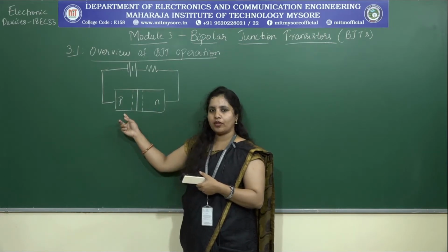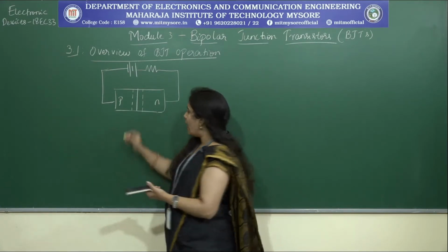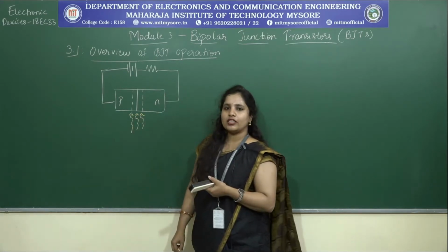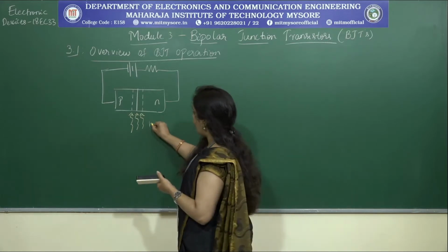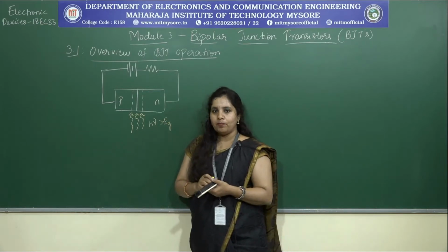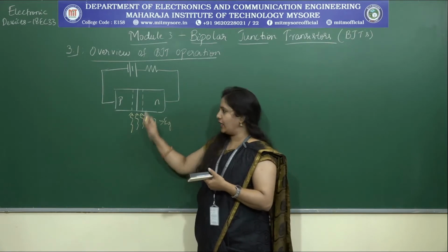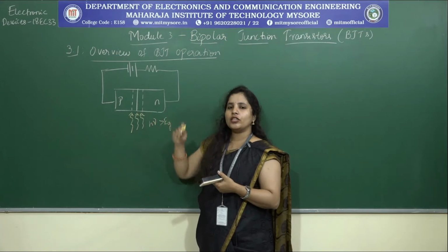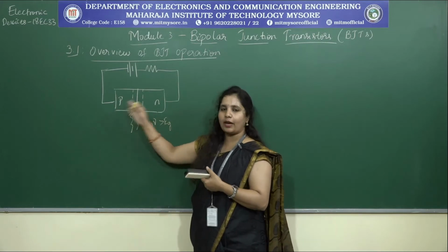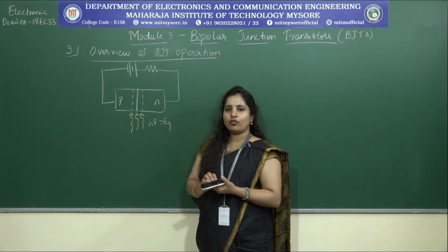increase the reverse current? One of the methodologies that we have seen in the previous session is to make light of a certain intensity fall on this p-n junction device, where the energy of the photon is greater than the semiconductor band gap. When this happens, it generates EHP pairs in the n and p regions, which in turn increases the number of charge carriers swept to the p-type and n-type materials. As a result, it increases the reverse current flowing in the device.